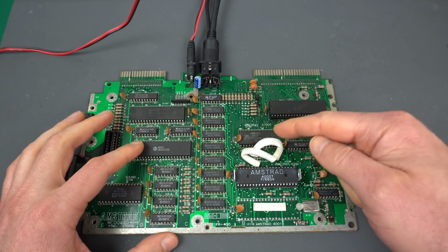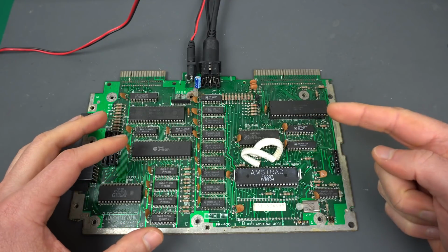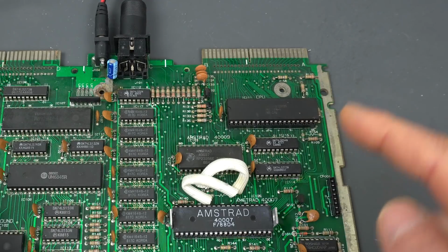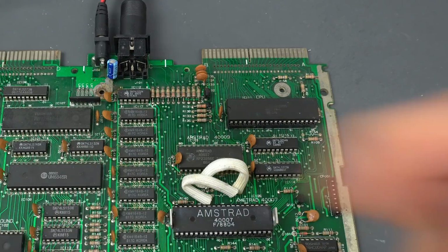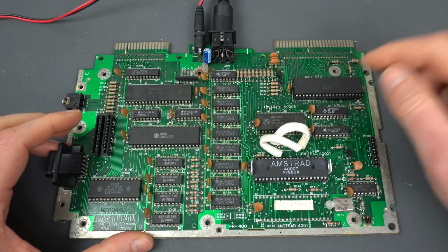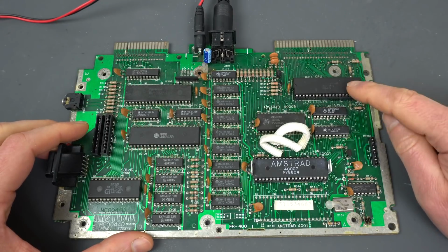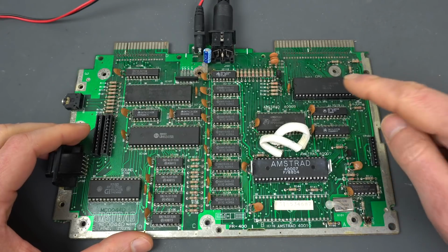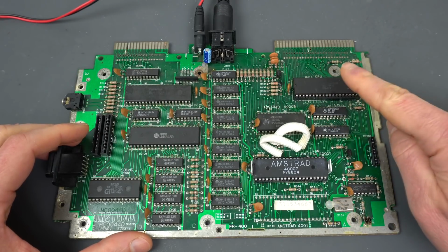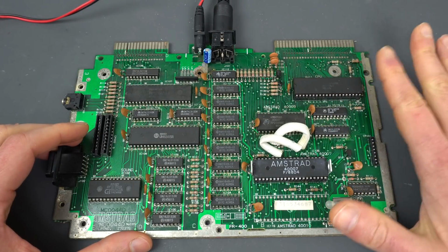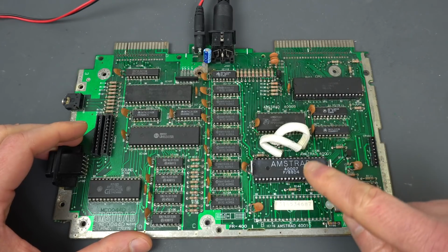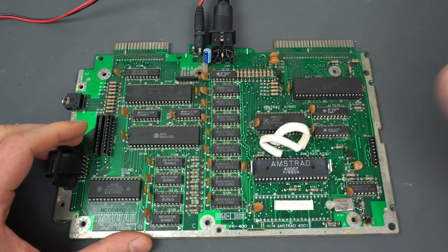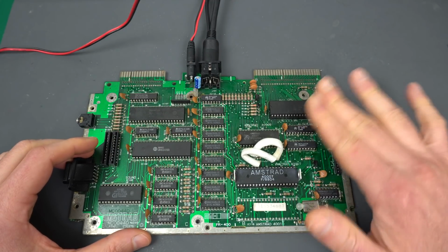So if it wasn't a ROM problem, maybe there's something that prevented the CPU, the Z80, from initializing the CRT controller correctly. I didn't even bother checking the Z80 because we're getting some image on the screen. And if your Z80 is not working, you'll get a black screen because the gate array is using some of the signals from the Z80 to generate the video signal. And that's why I've kind of dismissed it up until now.